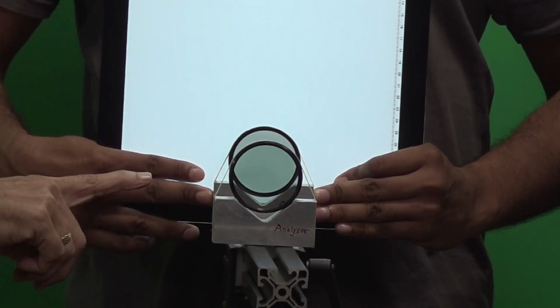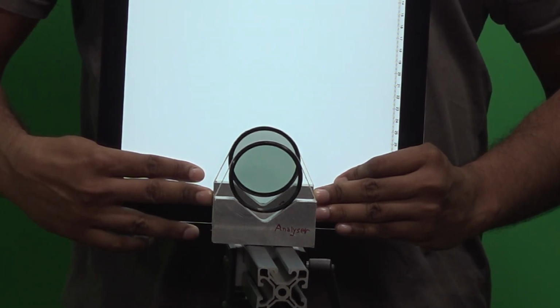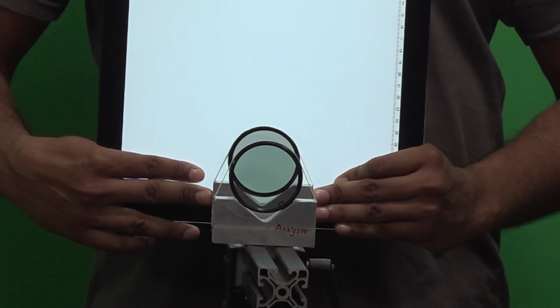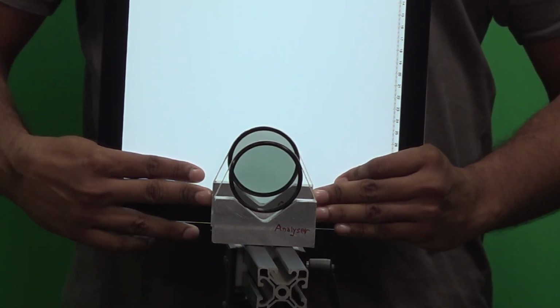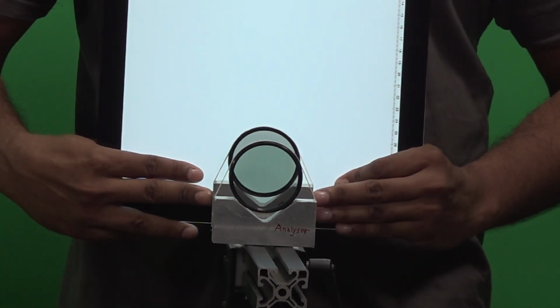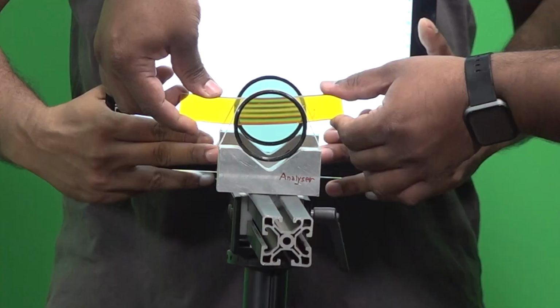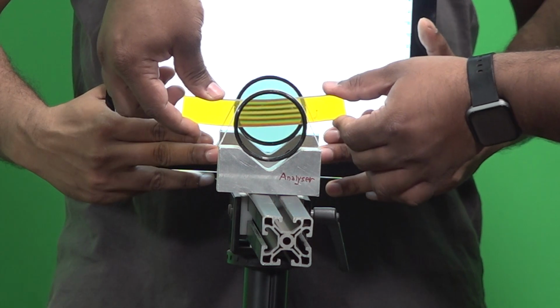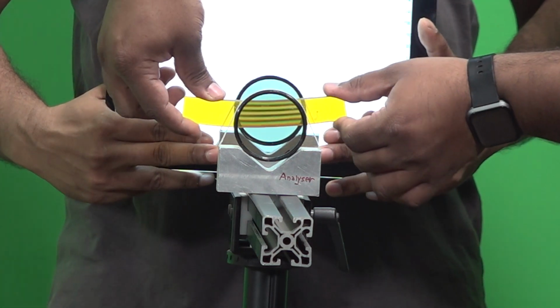So you have these polarizing filters available for a DSLR camera. You can have 2 of them, and you can even use a cell phone light, but because we are taking a video here, that light is not sufficient. So we have a light source here. Now you show the model which is under bending, and you will see a beautiful set of fringes. Fine. What you need is only a polyurethane sheet, and this costs you just 350 rupees each. So within 1000 rupees you can construct a homemade polariscope.